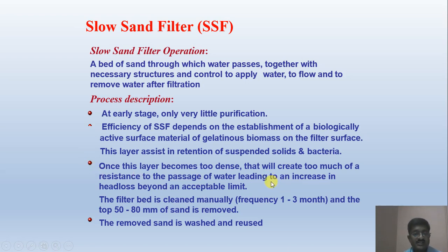Depending on that, we have to keep the functioning of this layer. The filter bed is cleaned manually. Depending on frequency, every 1 to 3 months, the top 50 to 80 millimeters of sand is removed. Then the removed sand is washed and reused. Rewashing is carried out.